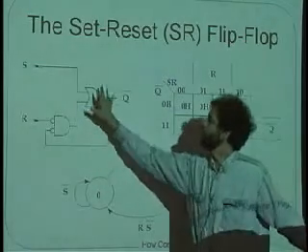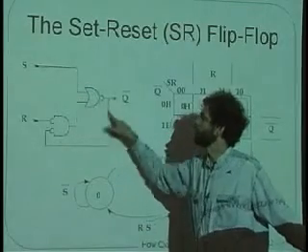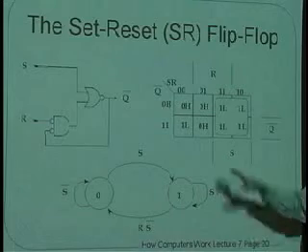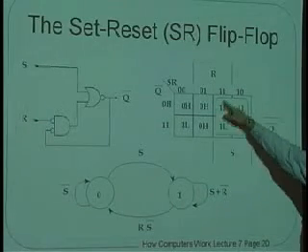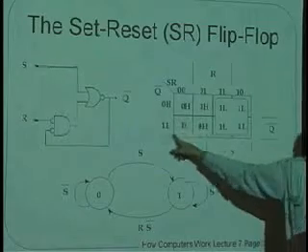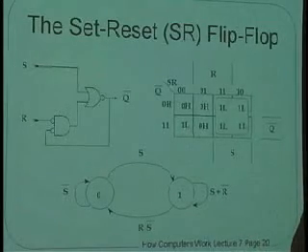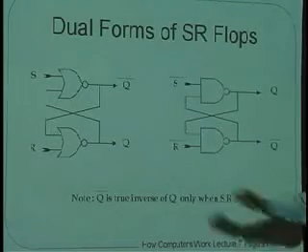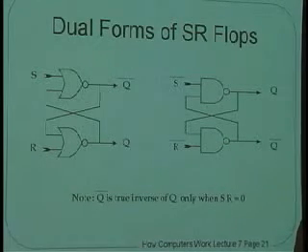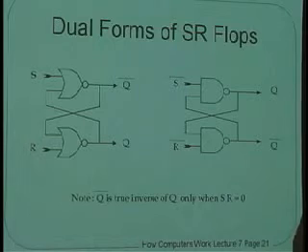It's just a transformed version of the transparent latch that we're looking at here, and the general notion of a logic circuit with one bit of wire feedback is exactly the same. And the reason it works is, again, because the K-map, which has this term in it, and also one more here, which I haven't drawn in, is hazard-free. So this is just by way of things. Here's other ways that people draw the flip-flop. It's kind of a cool thing to look at. In your spare time, you should play with these things and see that they work the same way.